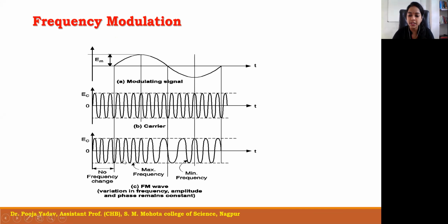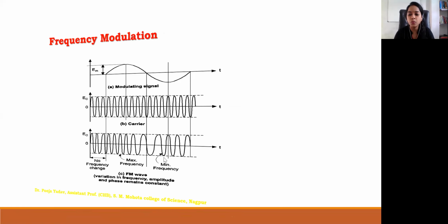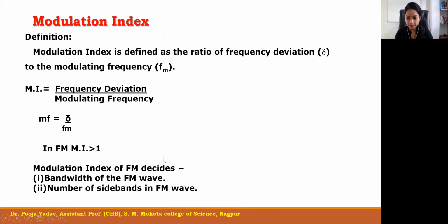signal. So how in frequency modulation do we do it? We vary the frequency of this carrier according to the amplitudes of this modulating signal. So here if the amplitude is maximum, you will have the maximum carrier frequency over at this place, okay, and here we are having very low amplitude, means it is in minus, so you are having a minimum frequency. So this is how we are varying the signal, we are modulating the signal according to what, according to the input sine wave.